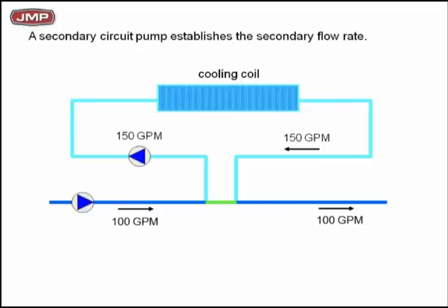So here we go. We add the pump we talked about. And now we have probably the first time you've actually seen the total simple little circuit of primary, secondary. Primary pump, 100 GPM. Secondary circuit in this case is 150 GPM. But now we have a primary secondary setup, and you got the definitions involved. So let's have a little fun here. If I've got 100 GPM in the primary loop, I'm showing a pump in the secondary loop taking out 150 GPM. Is that possible? Absolutely. There's no reason it couldn't be.